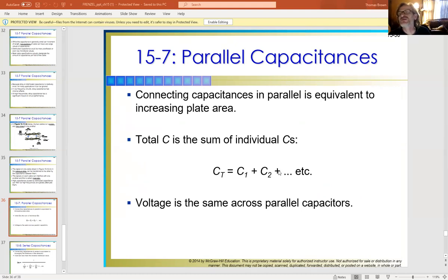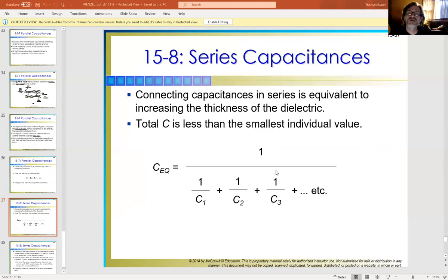And then to really mess with your head, capacitors in series are done just like we did resistors in parallel, where they don't just add up. You have to literally do this. You get your capacitive equivalent. Let's say I had 3 different capacitors in a series configuration, and I wanted to find out what my overall capacitance is in the circuit. I would have to do this formula.